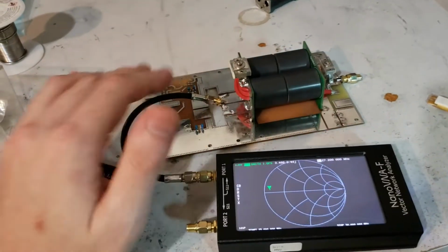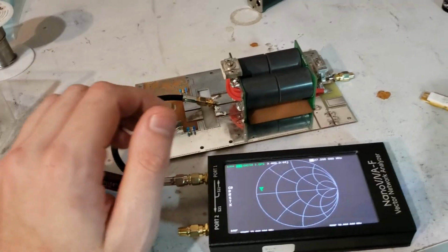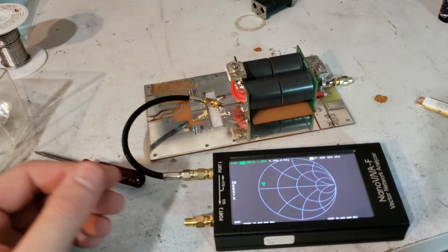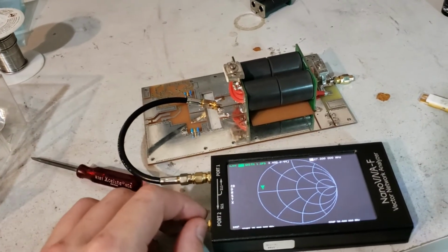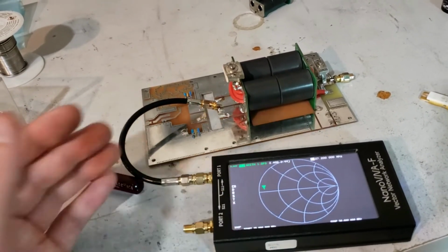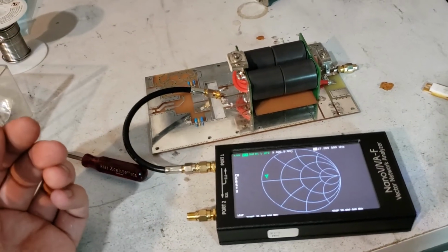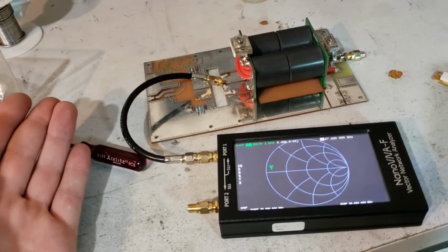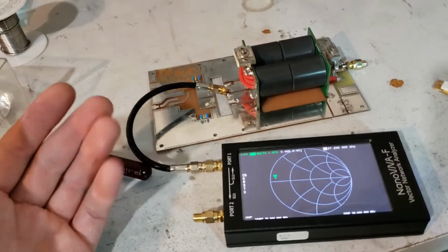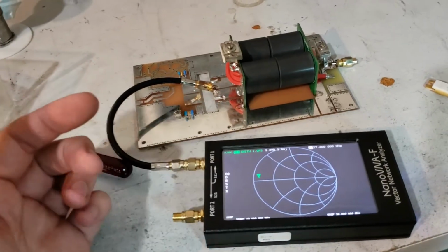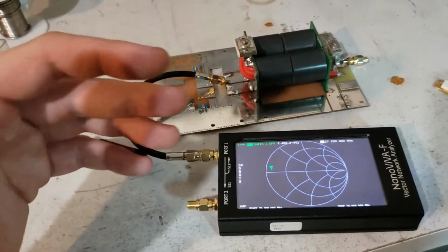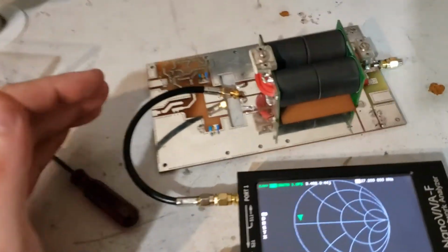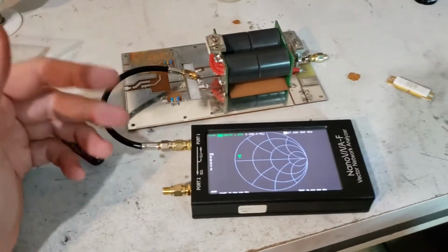So if you were starting from scratch with a transistor that you've never used before, you're building an amplifier, you have no idea what the impedance data is, there are lots of tips and tricks to get you in the right ballpark, even if you don't have a data sheet. If you know what voltage your transistor operates at, what the maximum current is, and what the approximate power output is, you don't need a data sheet that shows you impedance numbers. There are tips and tricks to get to that, but I'm not going to cover them in this video. Just know that they exist, and you'll probably find them in the Motorola data sheets. I think that's where I learned pretty much all of these tricks.